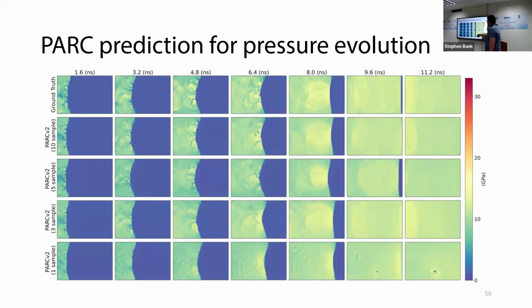But as a matter of fact, in this case, the full resolution model trained directly on the large scale simulation, after 10 samples, actually tends to develop a better, more crisp shock boundary, the shock front. But I guess that's the inherent trade-off between the full resolution model and the low resolution model.